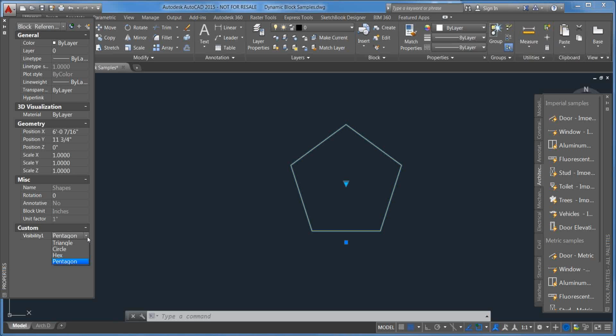And Chris asks, can we make dynamic blocks pull equipment information from a database? He wanted to push information to the database earlier, and now we're going back and pulling stuff from it. You can include attributes in your dynamic blocks, and they would behave like other geometry in the dynamic block that you could set them up to display. However, I don't believe there's any method by which you could pull data.